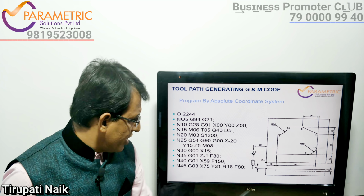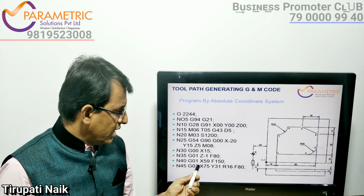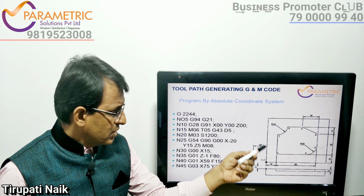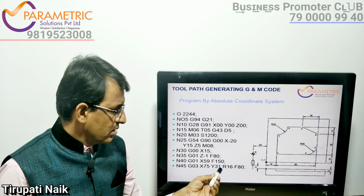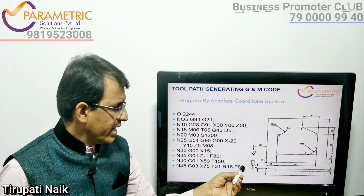Then the third point is N45, G03, that is circular interpolation of a 16 mm radius circle, and the coordinates for the third point are X75, Y31, and the radius is R16, and feed is F80 mm per minute.